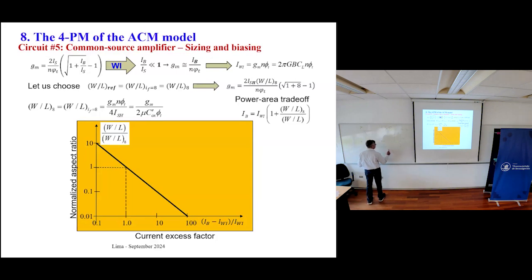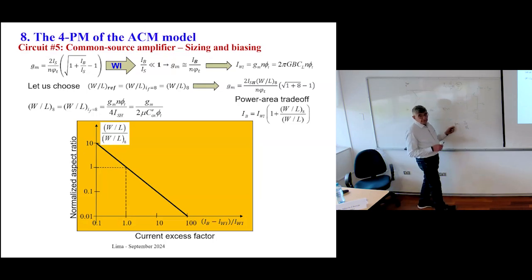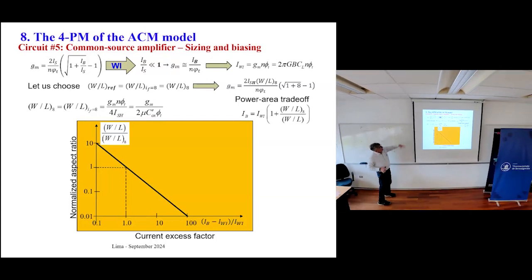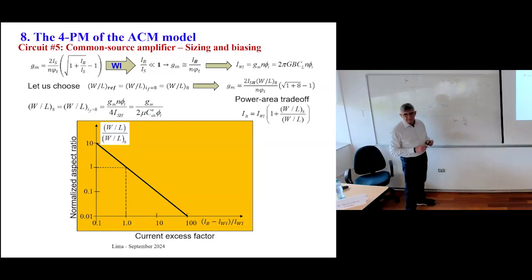And the weak inversion, you know this from bipolars. Do you remember this? The transconductance of the bipolar, which is the dependence of the collector current on VB, is IC over phi t. Okay. In the case of the MOSFET, you have almost the same. This would be ID, which is called IB in this example. IB equals ID. And there is another factor here, which is N. But it's almost like in the bipolar.